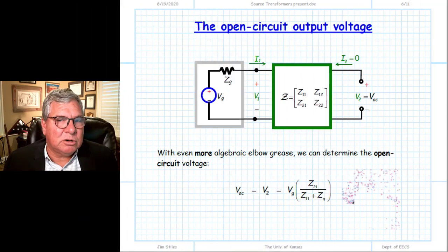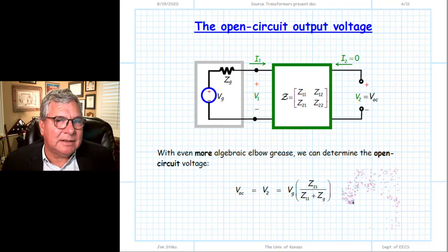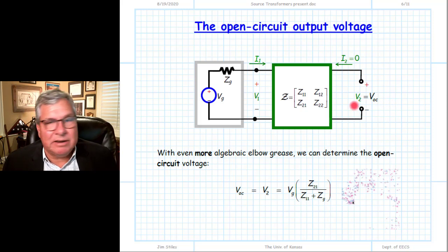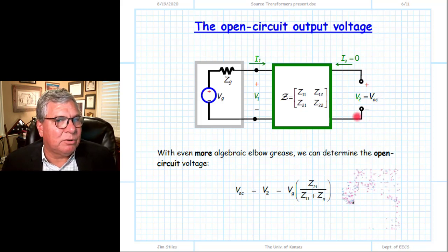When we're done finding the short circuit current, we need to move on to the open circuit voltage at the output port, at port 2. We find it pretty much the same as we did the short circuit current. Really, the only difference here is we changed the device equation for the equation attached to this output port.